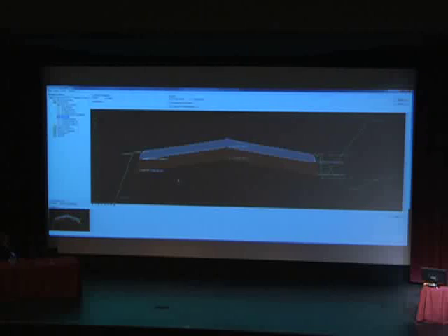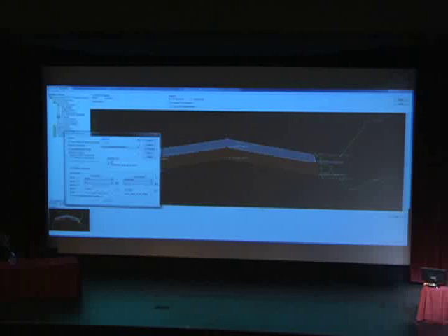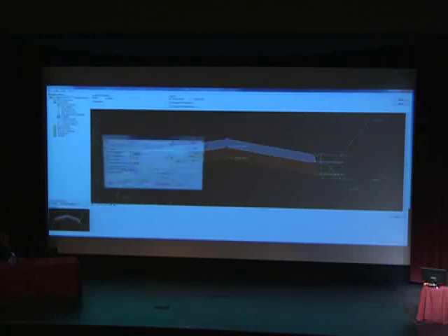Basically anything that's closed is going to give me cubic yardage. Anything that's aligned could give me square foot. And all those points there are all constrained, right? So each of these points, that point right there, has a horizontal constraint and a slope constraint. It's a little blurry to see, but those are 2 constraints. And then there's labels here at the bottom. Those labels are parametric constraints. What that allows me to do is click on my corridor anytime and change the values.